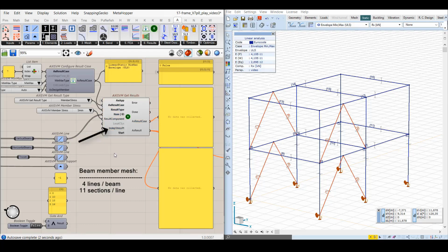Just a very short explanation about this feature. The default value is false, thus the various stress calculation points will have the value corresponding to the queried extreme components combination. If this input parameter is set to true, the various stress calculation points will have the respective extreme.